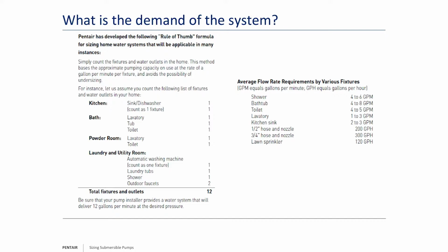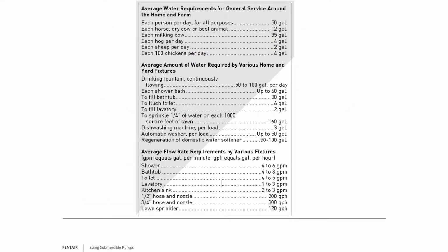Now, if you did my seminar earlier last month, we covered submersibles with a basic curve. And there too, we started with how do you size it. Now, for residential application, you do the fixture count method. You can look at the flow per fixture. However you choose to do it, that's fine. But understand, these charts are easily found. These were all found in my handouts, for example, that I give out for any class here in Delavan, or in Grand Island. We have these engineer books.